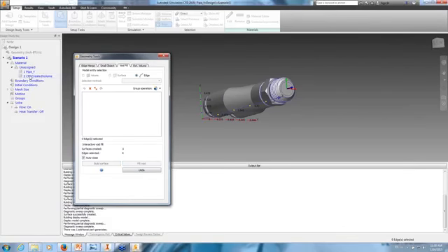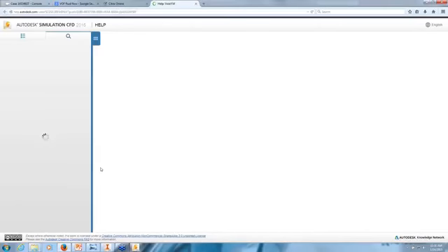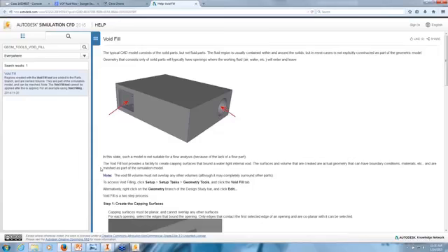While that's going through, one thing I just want to point out, for somebody that's new to the software: let's say you bring up this geometry tools window and you don't really remember the workflow. In pretty much every single window or widget that floats, you'll see a little blue question mark. Right below the build surface button, you'll see a blue question mark. All these are context sensitive. If you click on that, it'll bring you right to the online help system for using the void fill tool. It talks about when to use it, how to use it, and things like that.